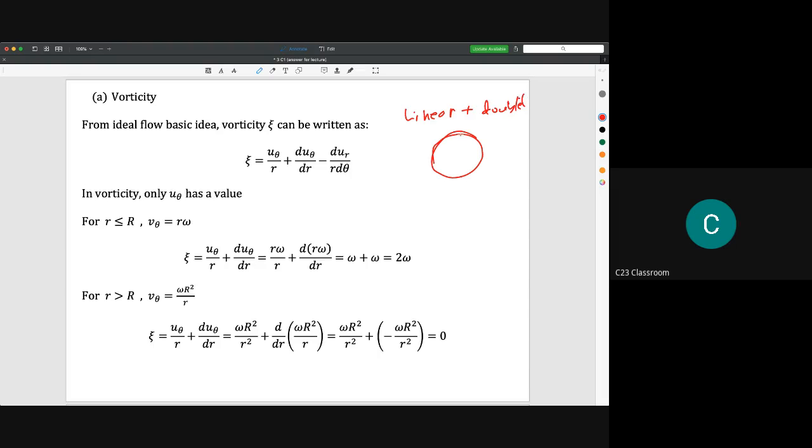Okay, and then you will get the cylinder and the linear flow like this. So this is the stagnation point. And then if you add the vortex here, the vortex will rotate this cylinder at a certain velocity, and the vorticity here is actually the circulation. So the vorticity is gamma, the circulation, divided by the area of the circulation. So we have the vorticity. In simple words, vorticity is telling you about the tendency of something to rotate.